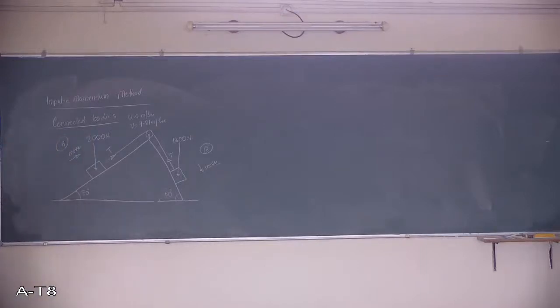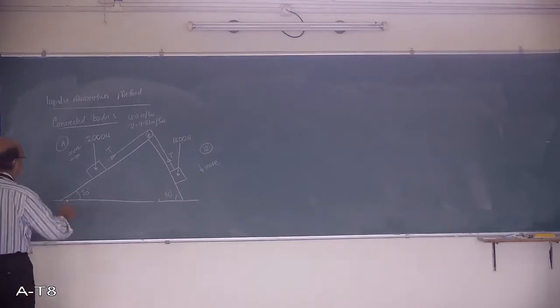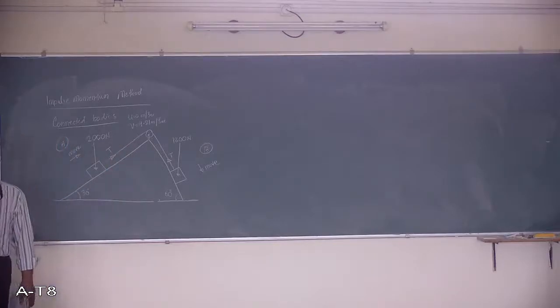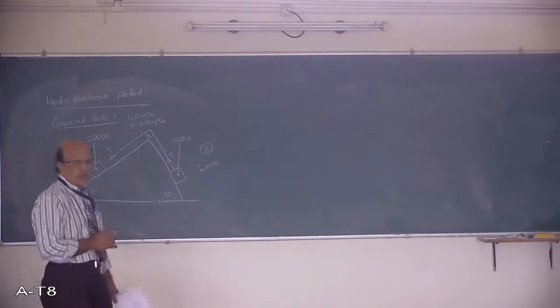So, one is you are required to work out time, second is you are required to work out tension in the cable. When these two parameters are asked, then I have to go the conventional method of applying the dynamic equilibrium condition for block A and write an equation. For block B, write another equation. There are two equations, two unknowns. You can solve those two unknowns.